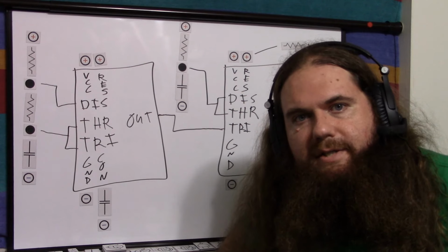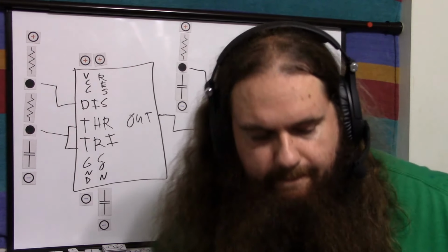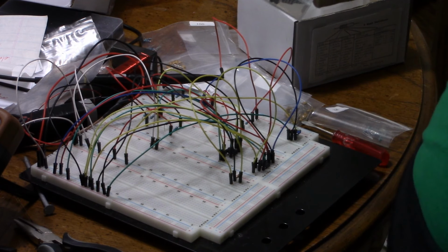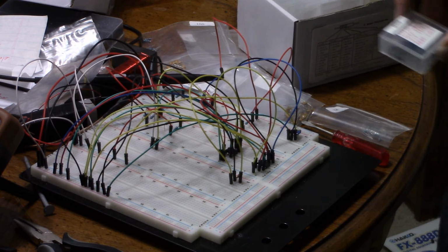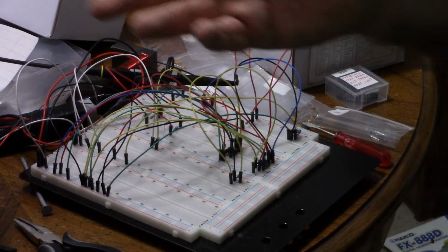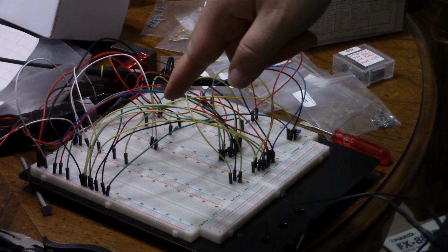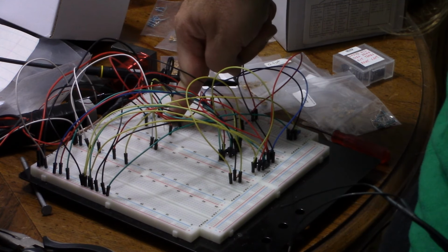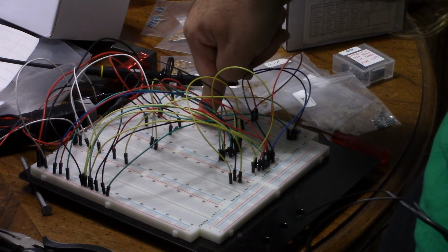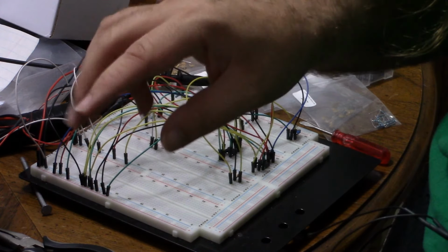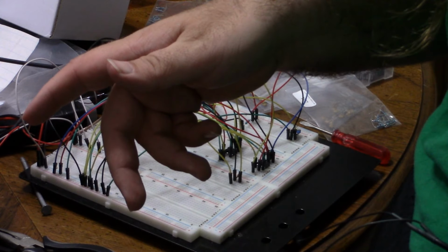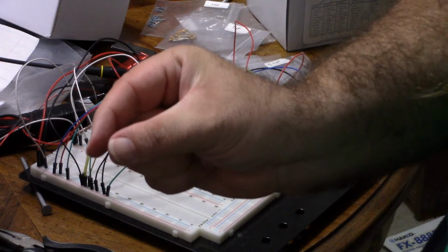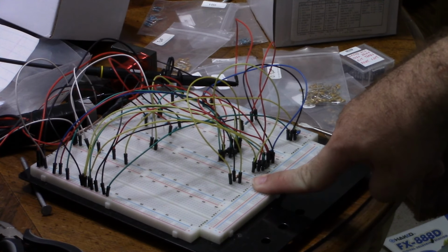So let me show you on my oscilloscope, and I'll give you some values I'm using. So many wires. So I have my two BJT 555 timers. They are the NE555P by Texas Instruments. I'm going to be using 5 volts for my power. So for timing the square wave, the astable, I'm using a 22k ohm resistor and a 1k ohm resistor. This gets me about a 15, 16 millisecond period. I'm aiming for roughly 60 hertz. It's close enough. So we get a nice, short, low pulse. And the capacitor is 1 microfarad.